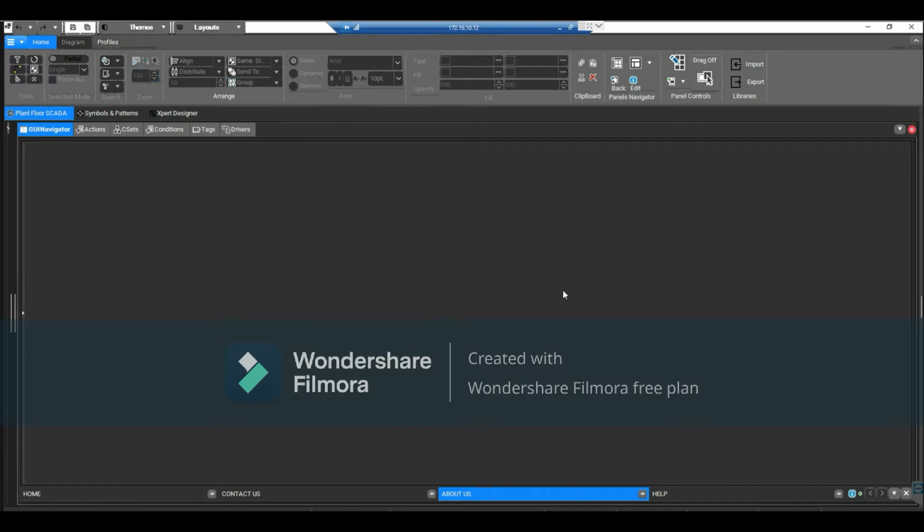In SCADA systems, each output field has its specific unit of measure, so you probably need to specify many settings, like: what is the unit of measure you want to use? The number of digits you want to appear in the GUI, to show more precise values. The sensitivity period and sensitivity record of reading the tag values. The choice to archive the tag. The min and max of the tag's value.